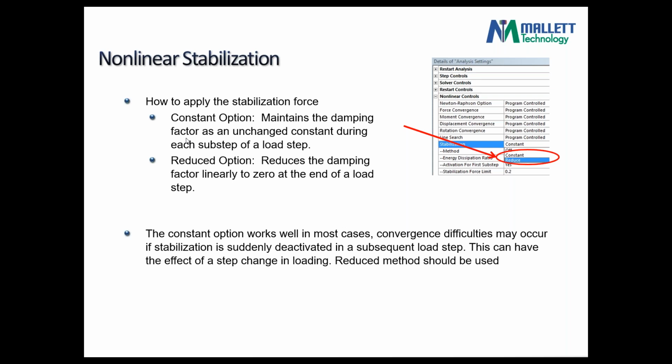So just in summary here, two methods. You can have it constant through the load step, or start at a value and drop it down to zero. They're really problem dependent. The key here is that the artificial energy you're applying needs to be known to you, and you need to see what it is, and then most likely you'll go back and forth between different solutions to quantify the results that you have and qualify them.